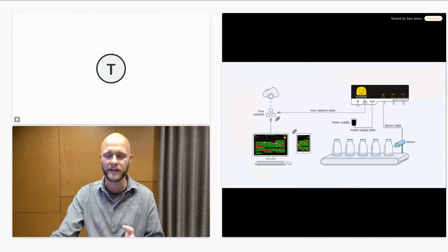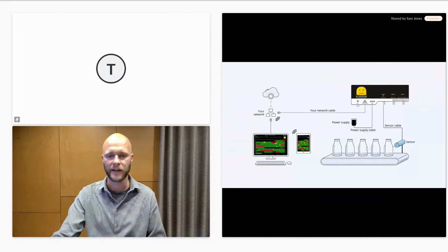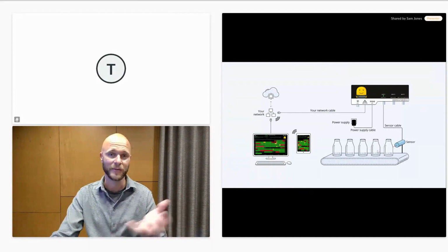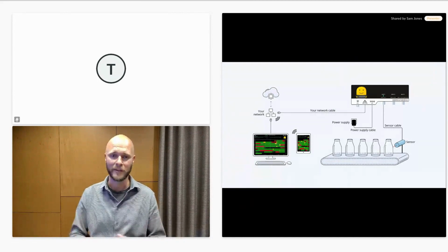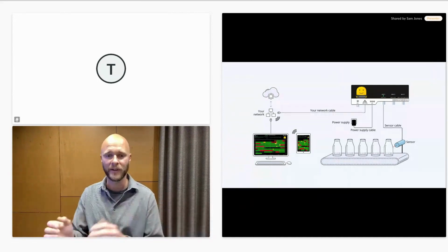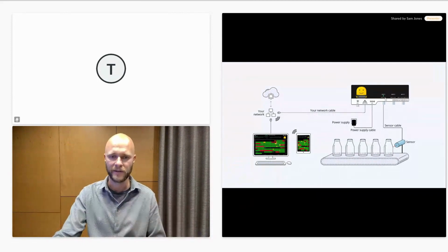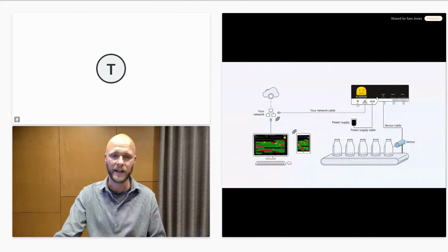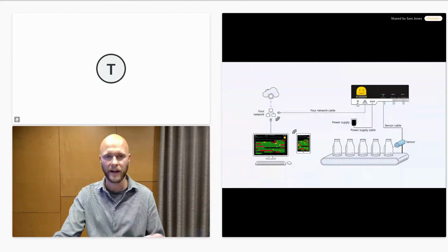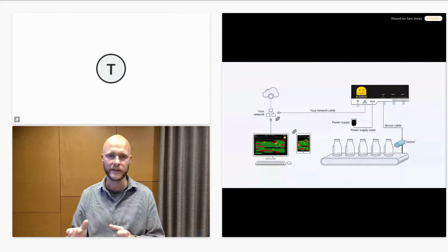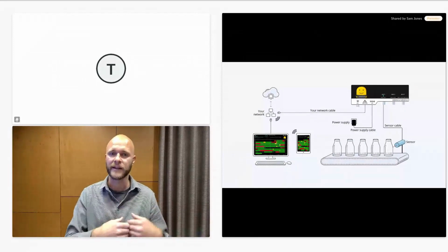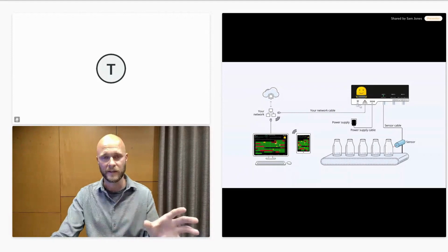What we've got on the screen here is the most typical setup. So this is an optical sensor counting units as they move down the production line. Obviously, on the image here, we've got bottles, but this could be anything from cement bags, fertilizers, window frames, you name it, but counting products as they move down the line. Those signals go into the IoT device. The IoT device has 3 inputs, so we can actually monitor up to 3 lines at one time. The IoT device needs to be connected to the internet. We can do that either via Wi-Fi, Ethernet cable, and we also have new 4G devices as well. So we've kind of got all bases covered. That information is then pushed to AWS, like I said, processed, and then shown back through the Evocon platform. So this is one setup.